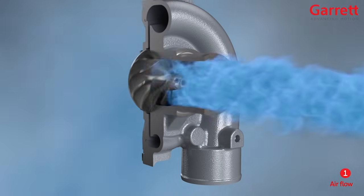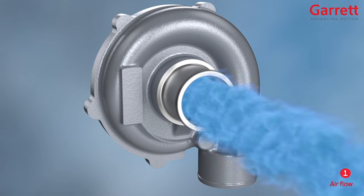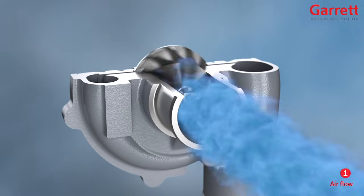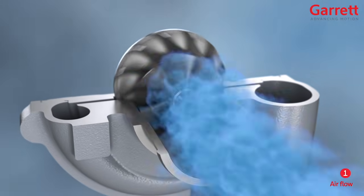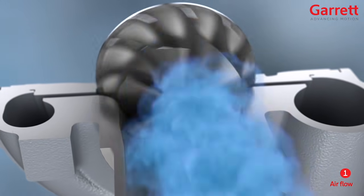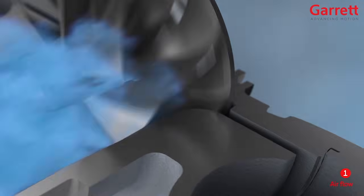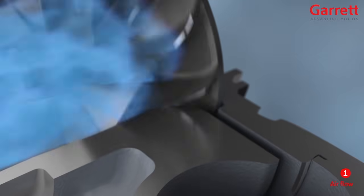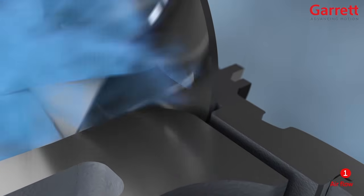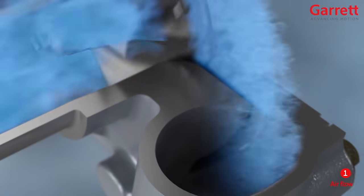When working at high speed and load, the air passing through the compressor reaches a velocity close to supersonic. So now the air contains a lot of kinetic energy, which is energy due to motion. The next stage is where the compressor converts the energy from kinetic into pressure energy by slowing it down. As the air passes out from the compressor wheel exducer or outlet blades, it passes through an area between the compressor housing and the backplate called the diffuser, which increases in area and allows the high-speed air to expand and slow down, and this creates a high-pressure zone.